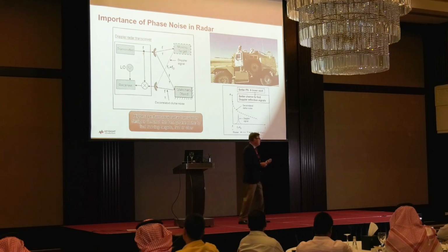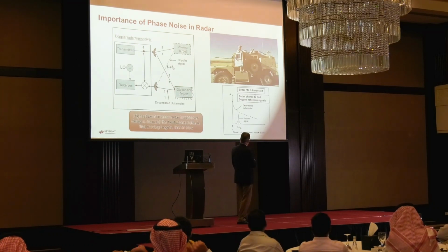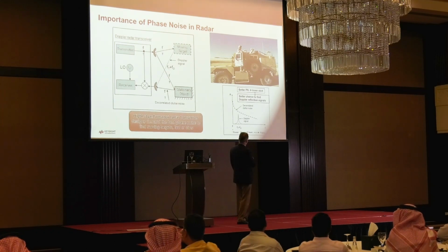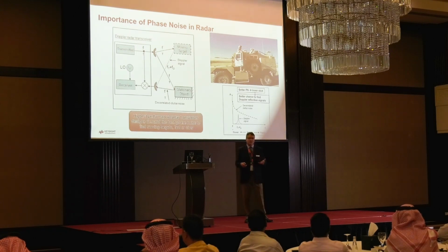It's also a problem for stationary objects, because remember, this could be a moving platform. There may be less Doppler shift, but the closer the reflected signal is to the carrier, even removing the carrier doesn't help, because the associated phase noise is still there and will prevent me from being able to actually extract out that reflected signal, which I need for my radar system to work.